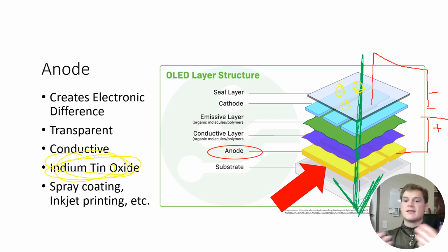Well, if indium oxide by itself is conductive and invisible, where does the tin come into play? What does the tin do? What it does is stabilize it. We have this indium oxide, but it doesn't really stay put. It doesn't harden. It doesn't really have that ionic bond. So what tin oxide does is it's the stabilizing agent.